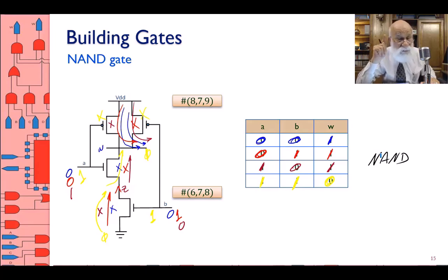It is structured such that, in a stable situation, never do the two parts conduct at the same time, and never do none of the two conduct. That means either the pull-up or the pull-down conducts. Period. But I said in stable situations.